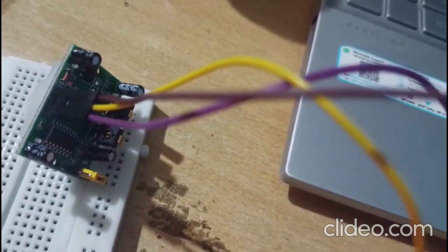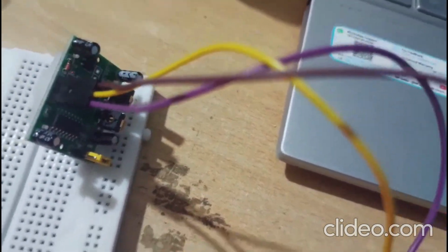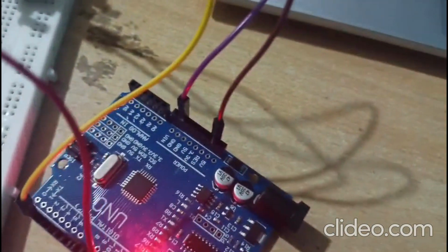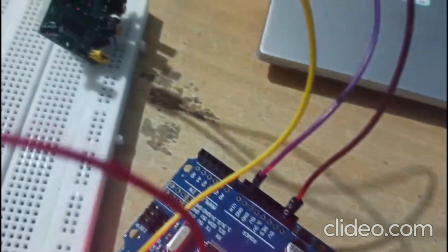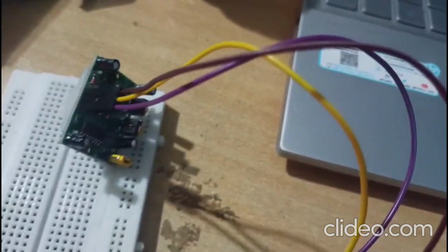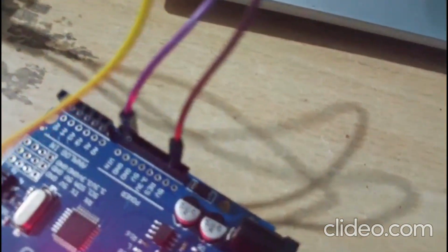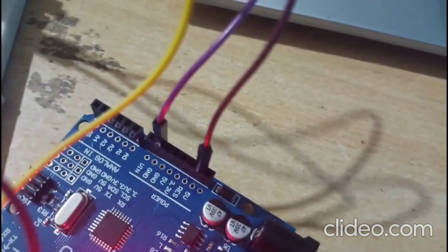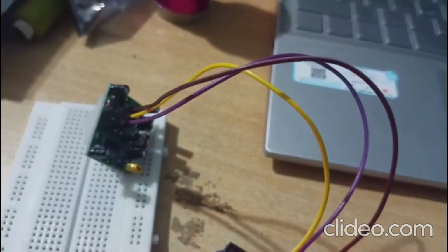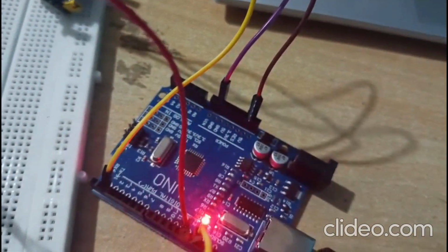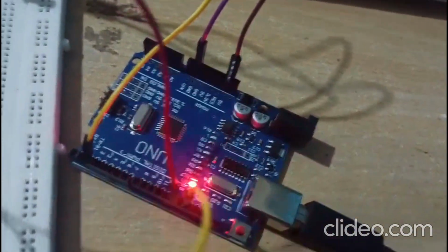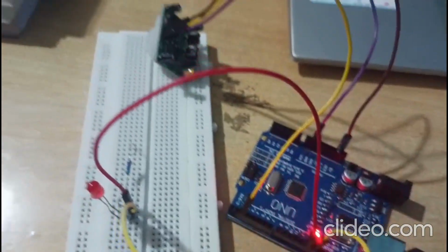And coming to the sensor part, the first wire, nothing but the brown wire, belongs to the voltage wire. Nothing but we have given it to the 5 volts on our Arduino. And next wire is purple color, which is nothing but ground. Negative pin we have given to ground on Arduino. And the middle wire is the output of the sensor. And here you can see that the connection is ready.